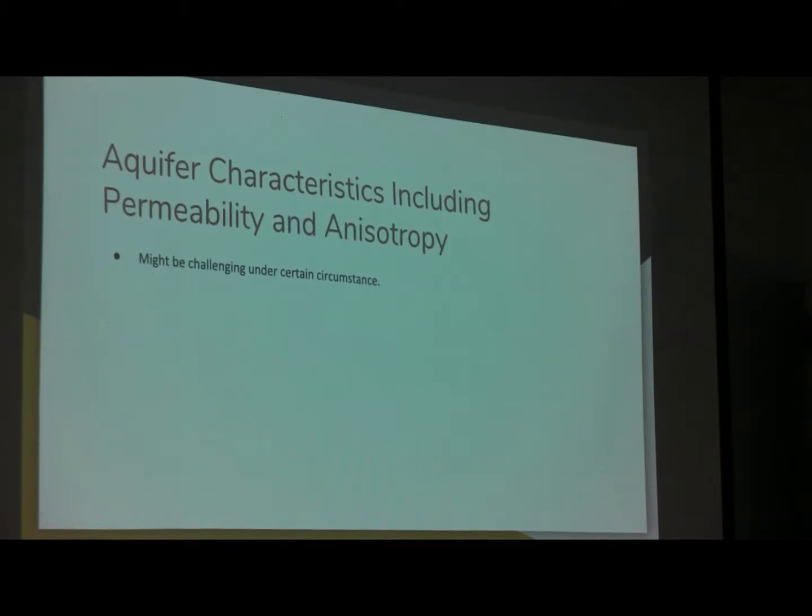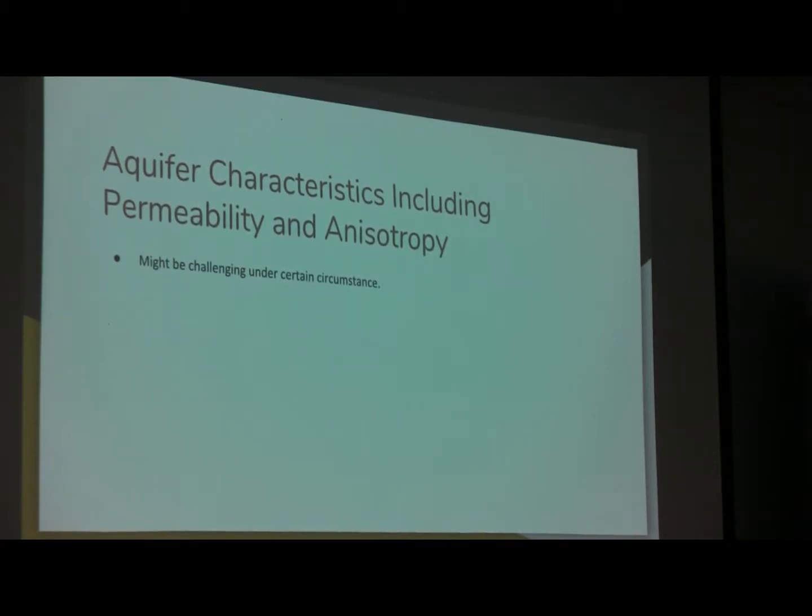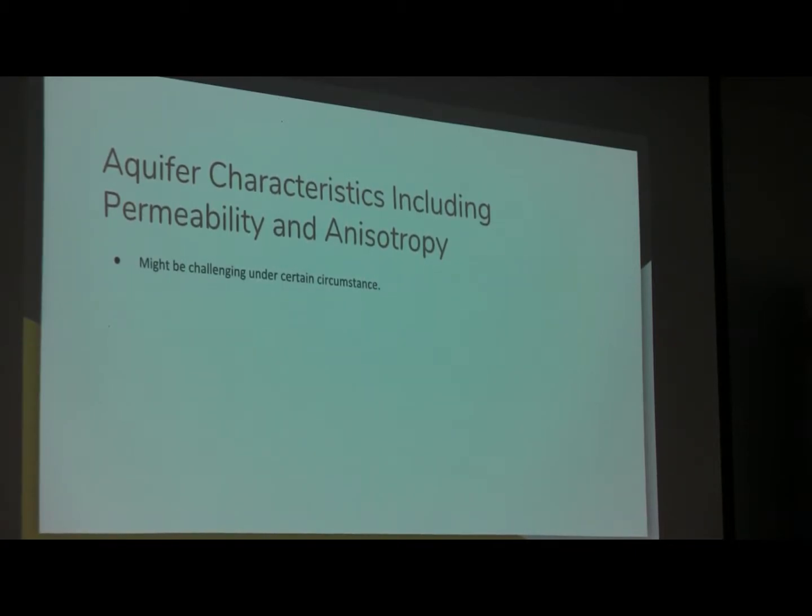And the second one is the aquifer characteristics. When air sparging encounters low permeability and semi-confining strata, it can sometimes bring challenges to the operator. For instance, if the contaminants of concern are located beneath a semi-confined unit, air bubbling into this unit could become trapped or travel horizontally, potentially facilitating migration of COCs. If COCs are located above and below a low permeable stratum, it may be necessary to install nested sparge points that are dedicated to treat both intervals.